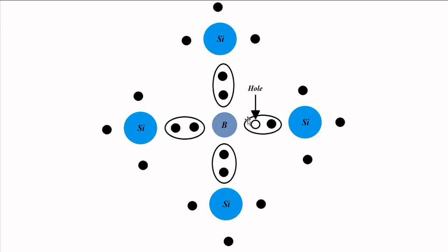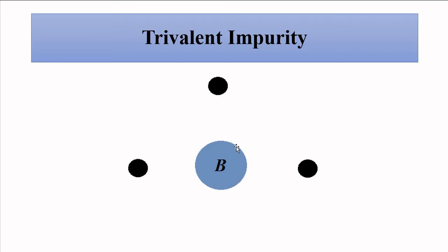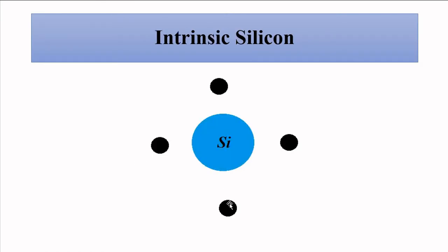electrons. So this vacant space, this vacancy for an electron, a free spot for an electron, is called a hole. This vacancy is created in the bonding process between boron, which has no more outer electrons, whereas silicon has four electrons.